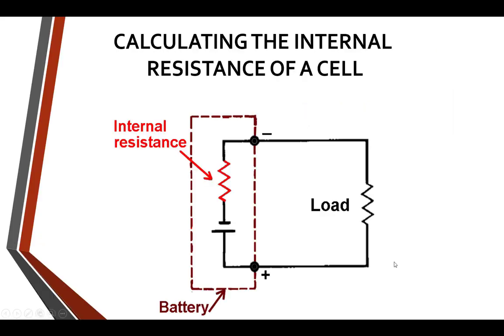Because of that internal resistance, as you see here, whatever this voltage is, when it's no load, when this load's not connected, we read a voltage here, and that entire voltage is across just the internal resistance. But now that I've put another load in series, the total voltage is divided among this resistance and this resistance. Now, obviously, you design a battery so that this resistance is much smaller than this, so that most of the drop is happening right here.